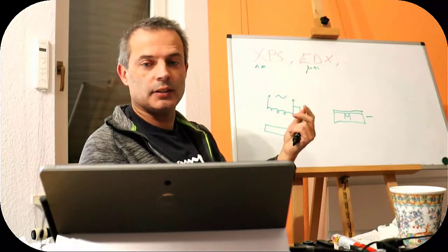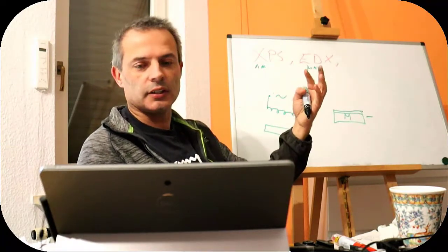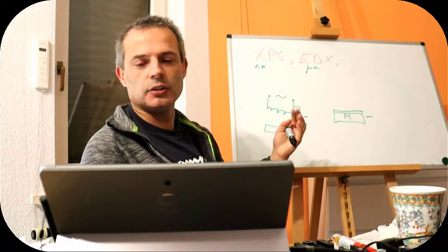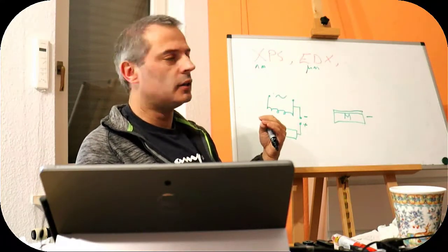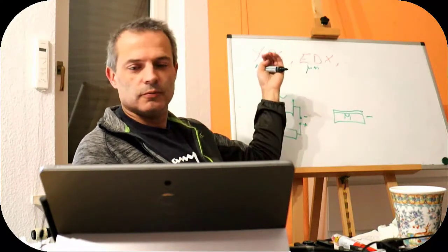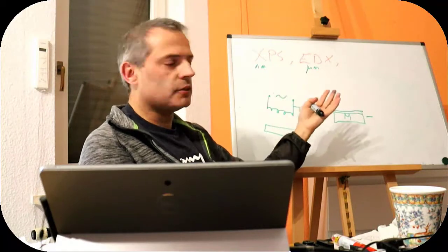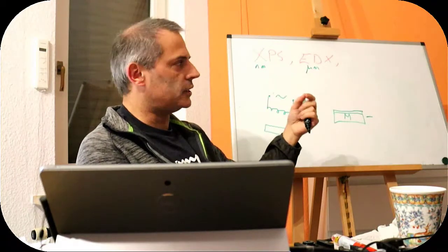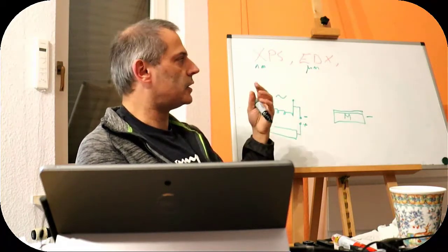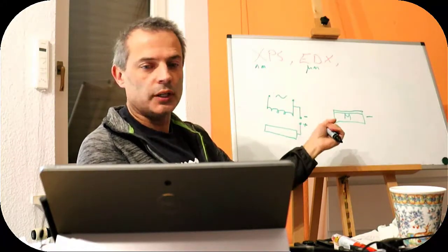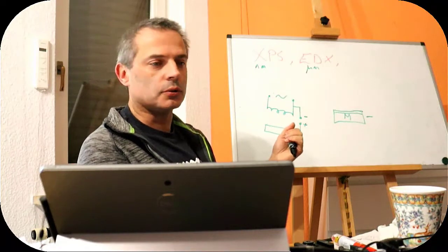We can make it better by making it pointier, because that focuses the field from the charge, and so we can sometimes do it at lower voltage. So in an alternative instrument we would have a very, very tiny tip, nanometers in size, and that will generate field emission. So we just have an electric field and no heat. We can have a field emission source.